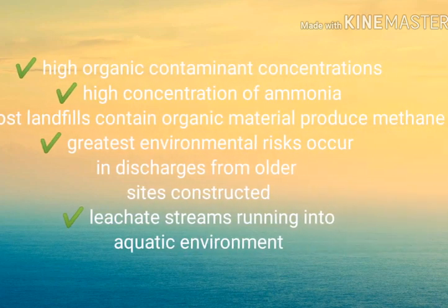Environmental impact. The risks from waste leachate are due to its high organic contaminants concentrations and high concentration of ammonia. Pathogenic microorganisms that might be present in it are often cited as the most important, but pathogenic organism counts reduce rapidly with the time in landfill, so this only applies to the freshest leachate.